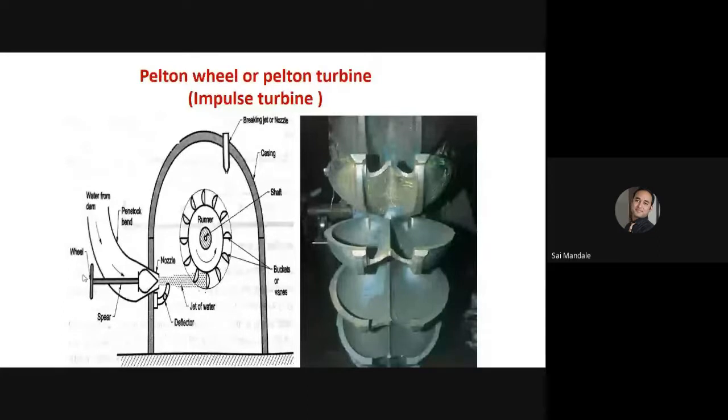So it is the same. It controls the quantity of water coming out of the penstock. Okay. Then this is a deflector. The deflector is used to reduce or divert or restrict the jet of water striking the cup. Then this is the jet. Then this is the casing, in which the turbine is installed. This is the braking jet. I'll talk on that now.